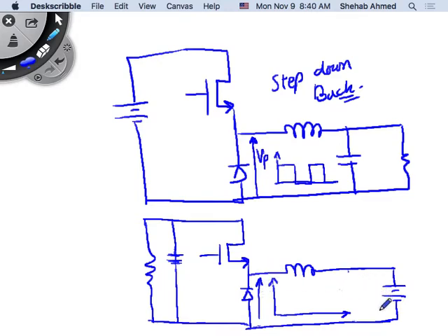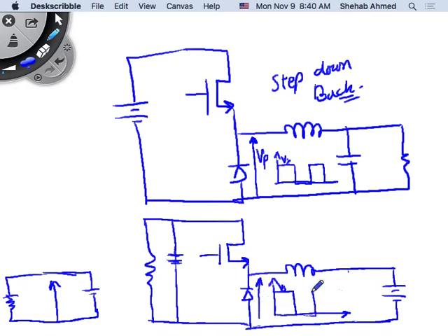So I have an input voltage here. So this is the circuit now. I have the source. This is a short circuit. The inductor is a short circuit. This is a closed switch, so it's a short circuit. And I have my output here. So what's my voltage here? Source voltage, right? So here the source voltage, and here, same thing, I have source voltage. On this side, the inductor, source voltage, and when the diode is on, I have what voltage here? 0. Same exact waveform.